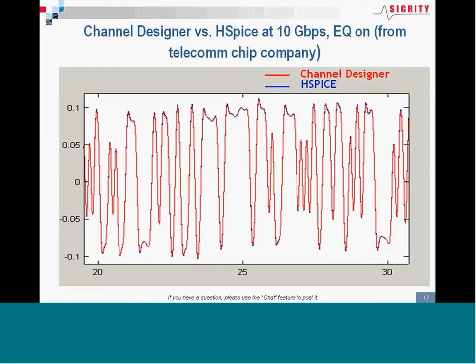So how well does it work? We've had to do quite a bit of correlation on these techniques by virtue of the fact that we work with a large number of SerDes IP suppliers in the industry, many of them producing their first IBIS AMI models. So we've had quite a few engagements like that. One key part of all those engagements is you need to correlate those models back to whatever golden source data they have, which is typically, in many cases, transistor level HSPICE.